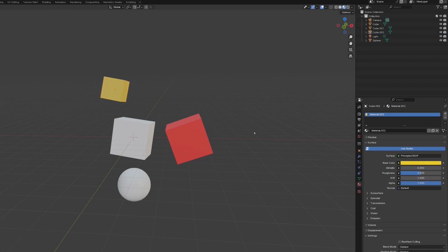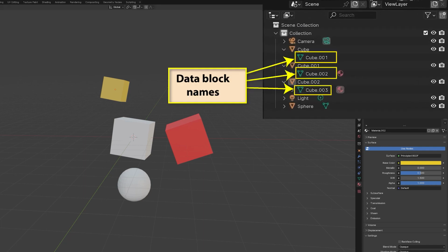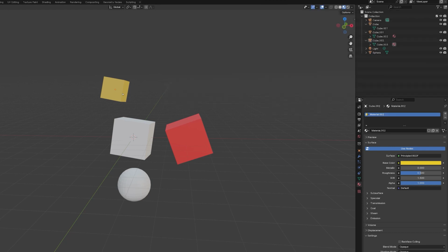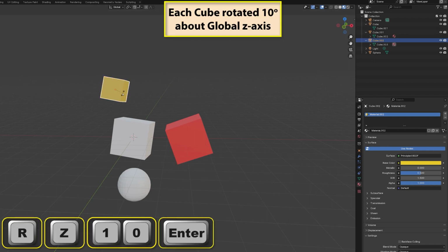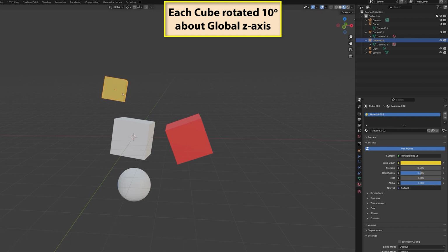There can be a downside to this operation because every object we create occupies computer memory known in Blender as a data block. So the more objects we create, the more data blocks we require. If we go to the Outliner editor and expand the object name entry, we'll see the name of the data block assigned to that object. Another problem occurs if we want to make a modification to the original object and all its copies. We may need to perform the change to each object separately.